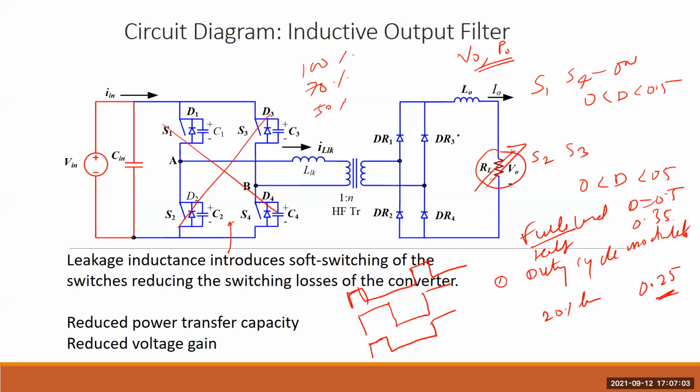Okay. So when the duty cycle is high, as high as 50%, the leakage inductance is able to store energy at the highest value. Because during this time, the entire current flows through this, which is I in, and the inductor stores energy from the full current, for example 100 ampere. So the energy stored here is basically half L I squared, with 100 squared.